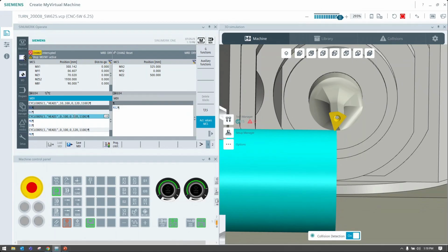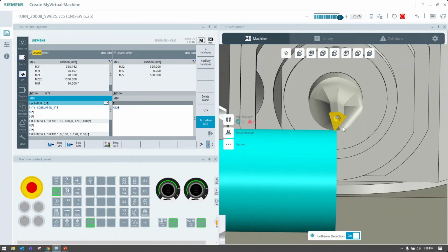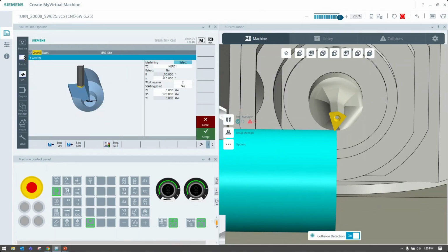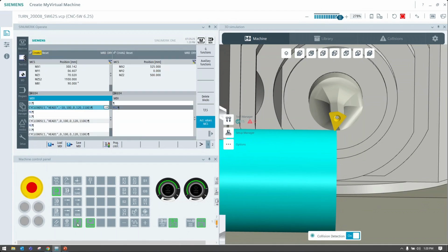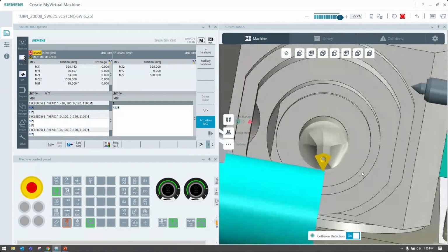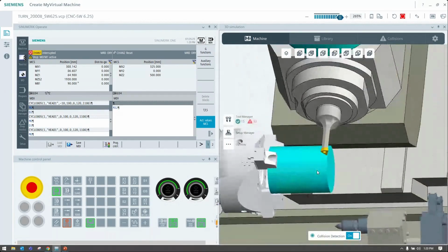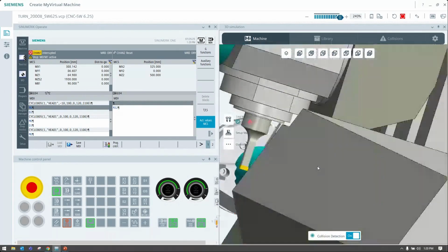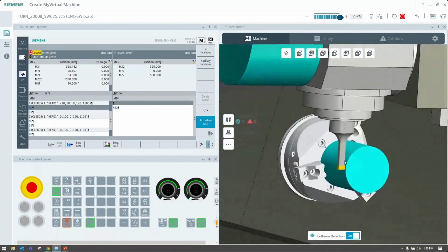And let's say I go back to that and I'm cutting this direction, but I want to come back the other direction. I could totally change that too. So this is where I can go -10 now, right? So this is super, super powerful. Now I'm pointing in, maybe a right-handed tool now. So I'm coming in there. So really powerful on the versatility of what edge I'm going to use per insert, right? But then if we think about this from a cutting perspective.